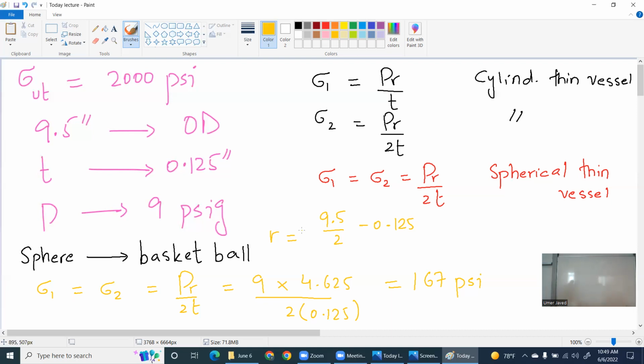Yeah, it is a pretty easy topic, but there are a few things that you have to realize. Remember that why am I using stress 1 and stress 2? Because interestingly, these are also the principal stresses. So remember this thing. I could have used sigma subscript hoop. I am allowed to, but I chose 1 because interestingly, these are principal stresses as well.